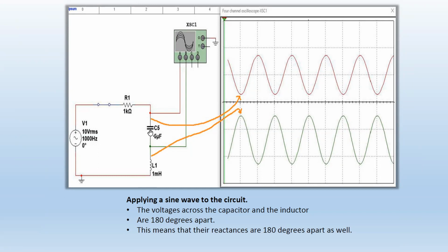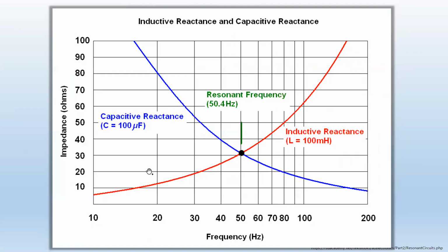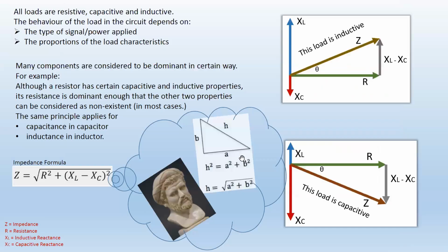So at the resonant frequency, if you have those two components in series, they're going to cancel each other out. It's just like if they were not there. At the resonant frequency, the impedances of those two are going to cancel each other, and it's just like if you throw them out and put a wire there. That's the resonant frequency. Why? Because they're same magnitudes, but they will have different angles. They will be opposite each other, so they will cancel each other out. All right.